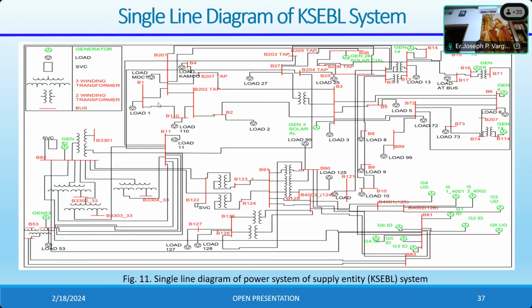This is the system considered, part of our system, starting from Idukki power station via Kalavasheri substation up to the 400 kV substation, Madakkathara. We have modeled the system. We have taken all the transmission lines, distances and lengths accurately, and the resistance, inductance, capacitance, everything has been taken very accurately, and the system has been modeled. The generator sizes, generator specifications, everything should be correct. Transformer ratio and transformer winding specifications should also be accurately recorded. Then only we will get the correct results.